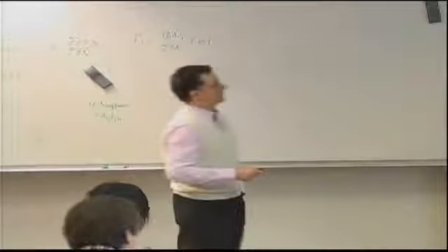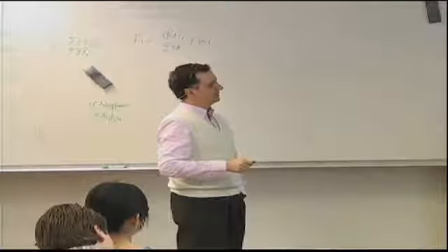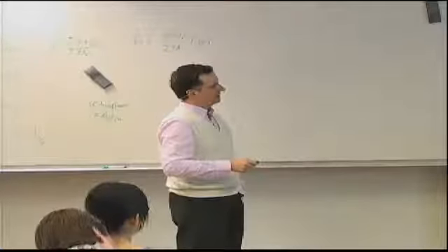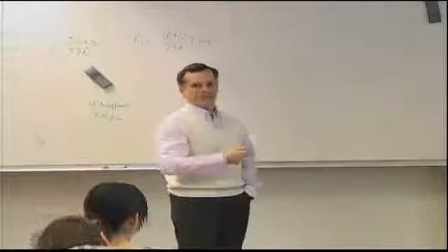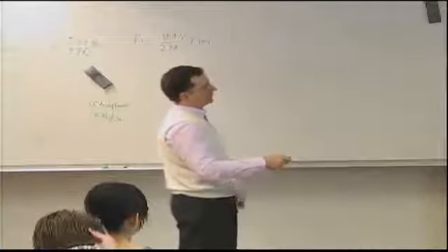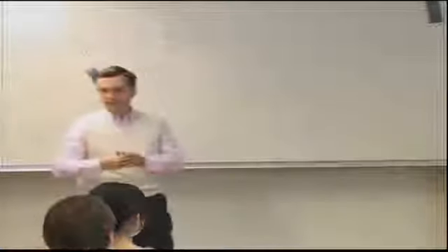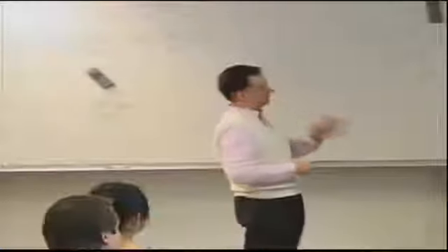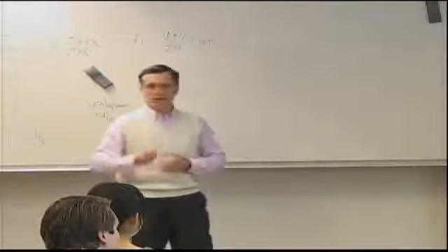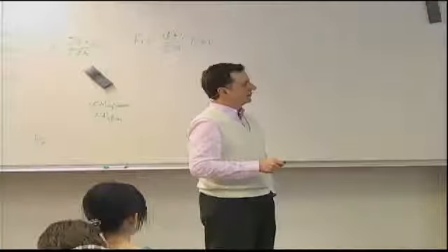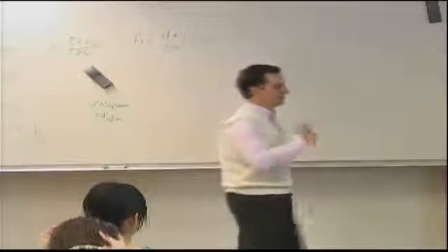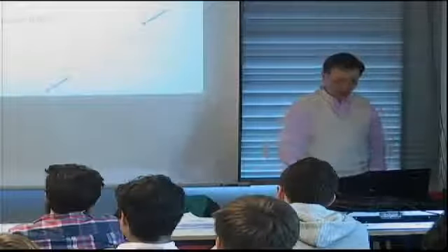Because it's simply supported, there is no bending moment, so minus D11 d2w/dx squared is equal to 0. In its general form, it would have a minus D12 d2w/dy squared minus 2 D16 d2w/dx dy, but because those involve derivatives with respect to y, which are neglected here because there's no dependence on y, this is our condition. So at the two ends, where the fasteners are, zero displacement and zero bending moment. Let's substitute our solution w into these conditions to see what we get.